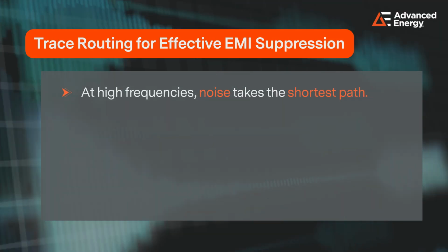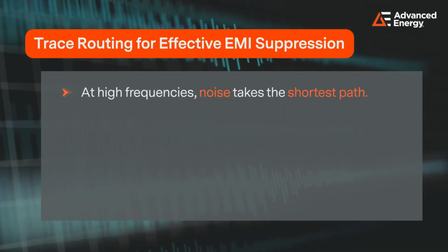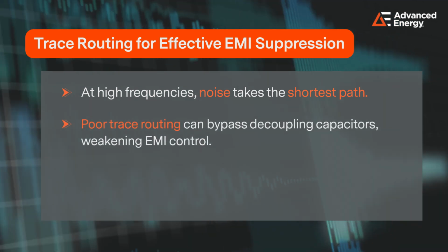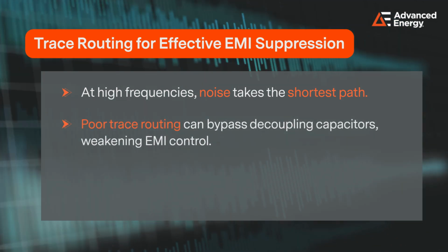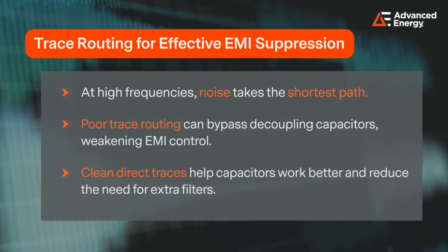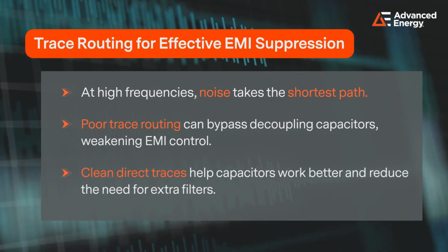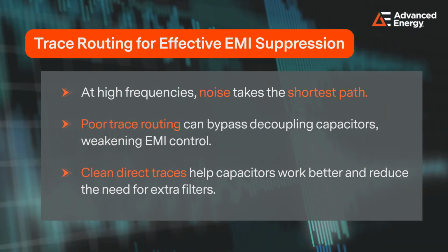At high frequencies, noise takes the shortest path. Poor trace routing can bypass decoupling capacitors, weakening EMI control. Clean and direct traces help capacitors work better and reduce the need for extra filters.